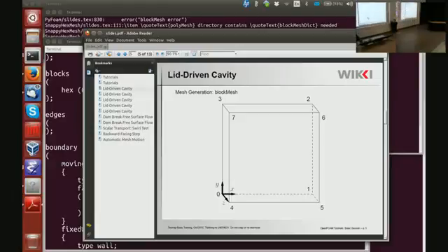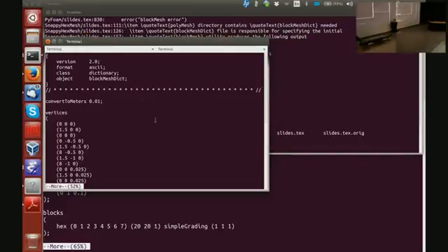So how does the normal sit? So you said the right-hand rule? As my professor of mathematics would say, the rule of the left foot, or obviously the right-hand rule. You can start from any point and walk around following the right-hand rule. But the face normal should be outwards. So your mesh looks like an angry hedgehog, so all of the arrows go outside. Okay, so let's take a look at the real example of what I'm asking you to do.